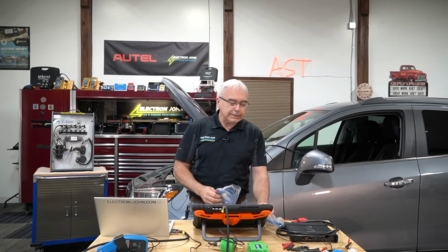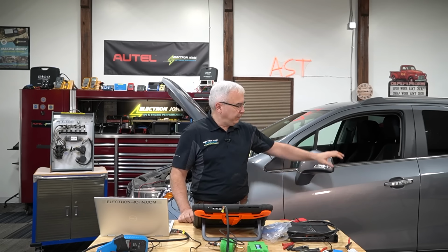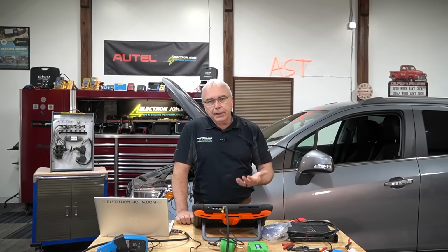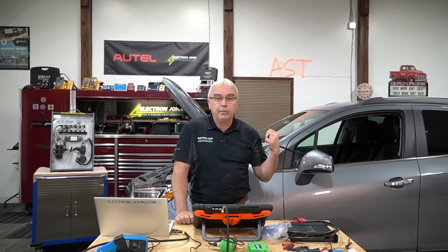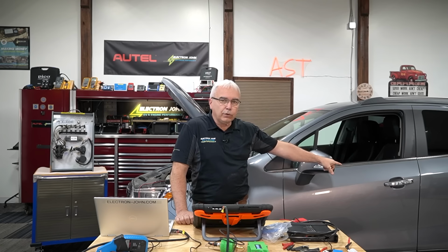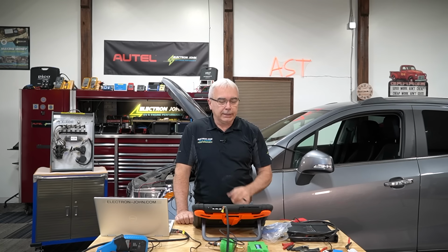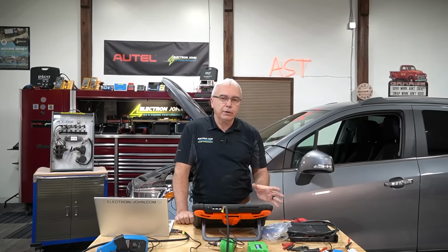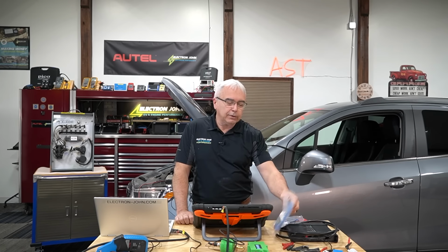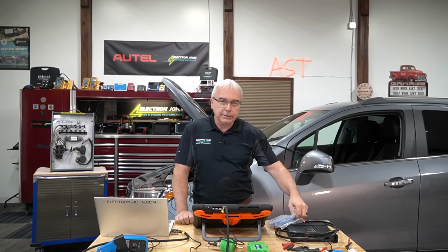So if I had, let's say, a no-start type of complaint, well, with a modern-day vehicle, it's probably got a push button start on there. I have to have the key fob inside the car. Also, it's probably got a little push button on the door handle that's supposed to unlock the doors as I walk up to it, all that kind of stuff. Anything that measures frequency on the car, I now can take my frequency style connector, hook it up to my scope, and I can get a lot of diagnostic test results.